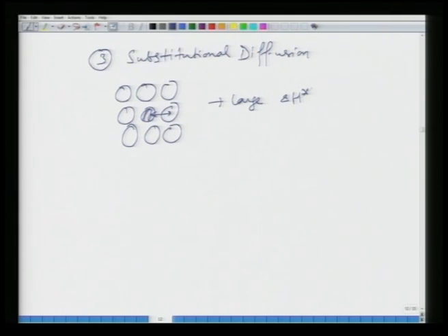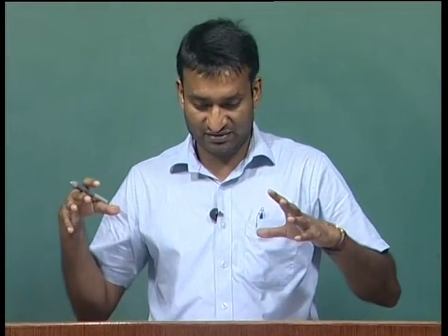So, a massive expense of energy is required, because then the whole lattice has to be dilated in the surrounding of these two diffusing atoms. So, these are the common mechanisms of diffusion, and as you can see, vacancy and interstitial mechanisms are more dominant mechanisms, because they require the least expense of energy because of significantly reduced requirement of dilation of surroundings for atoms to move.